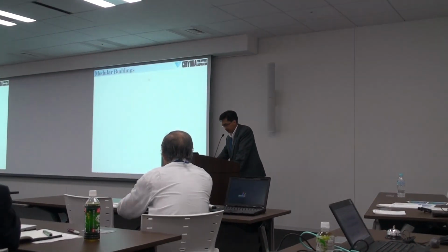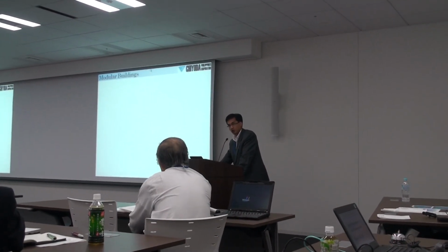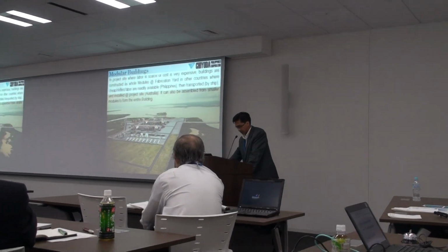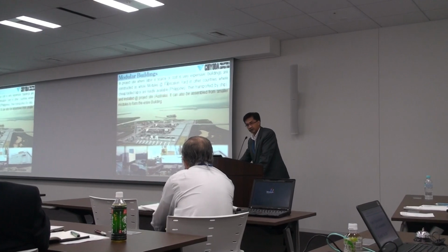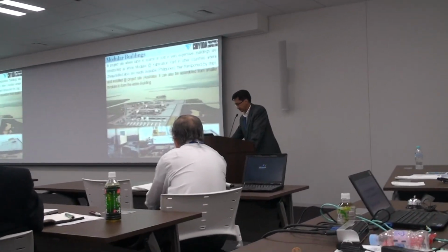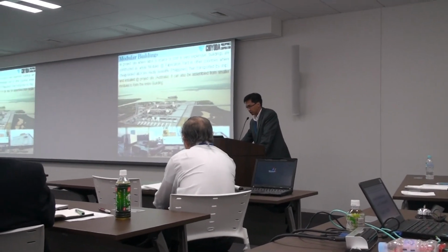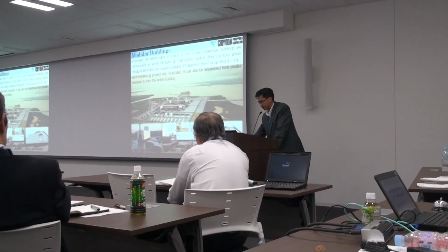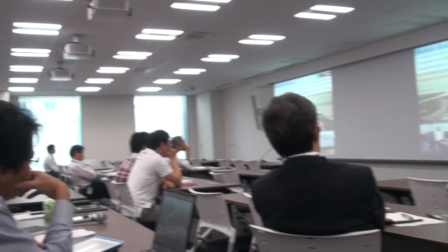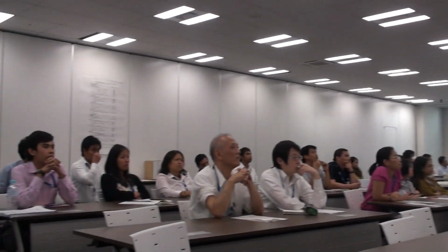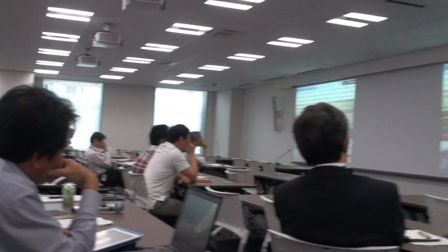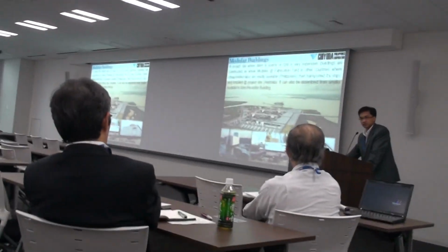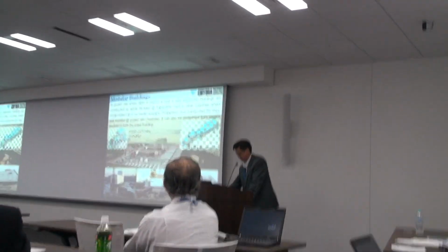Then now this building is the modular building, which is our current project in AGL. At project sites where labor is very scarce or very expensive, buildings are constructed as full modules at a fabrication yard in other countries where cheap skilled labor is readily available, such as the Philippines, China, or Thailand. Then they are transported by ship and installed at site in Australia. It can be assembled in smaller units or as the entire building.